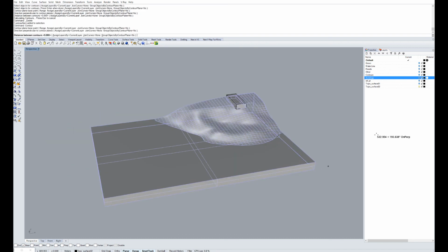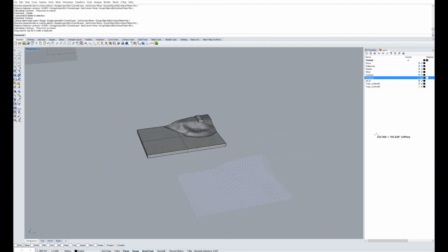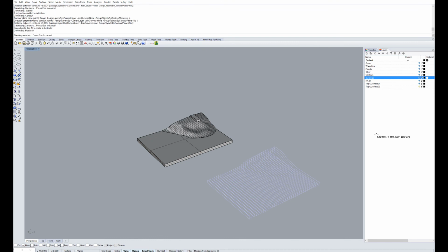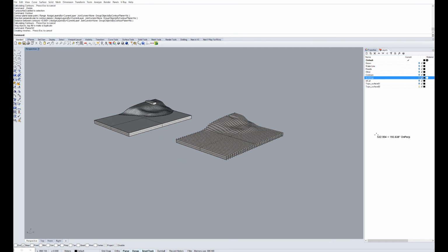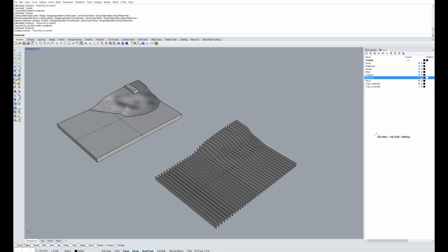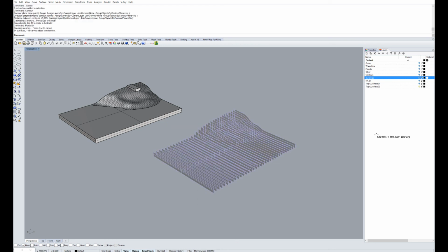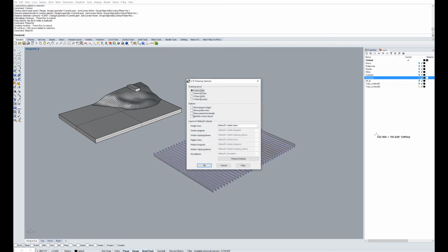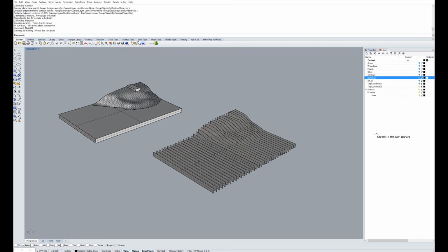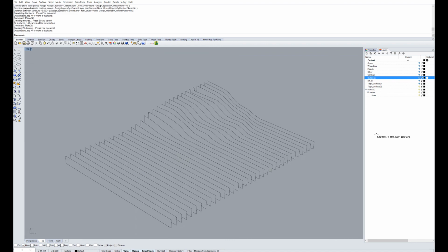And those could be used for things like, well, generating physical models out of this, or it could be used for diagramming. So this could create quite nice diagrams. So just a quick kind of tutorial. If we have this kind of geometry like this, and we select it, and we type in make 2D, and we go back to our origin in XY dimension, it generated lines out of that view.